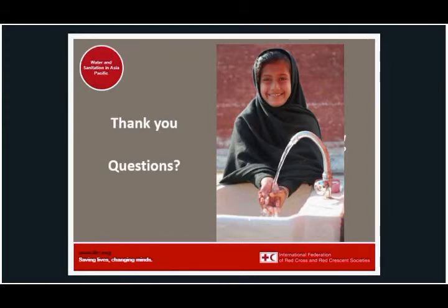The other one is what we call the onion tank or the Oxfam tank. They are open on the top, so you have the choice to cover or not cover. If it's raw water, we don't necessarily need to cover it. But if it's treated water, we will cover it. For the raw water, we are doing the sedimentation process, as Samuel explained. We will have to clean inside, so this will not be possible in the bladder. That's why usually we make sedimentation in the bigger tank, and these tanks are often open on the top to allow a better, faster cleaning.